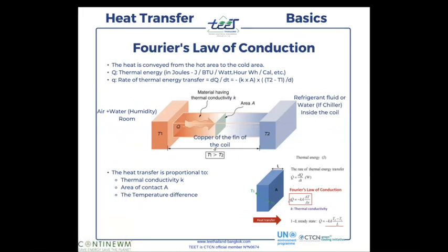You remember this, the quantity of energy is proportional to the delta T. Here you have T1 that is hot and T2. So if you want to measure the quantity of heat, that means the energy that is consumed by your AHU, how much the water absorbs the heat, which will result in the end on how much the power consumption of the chiller, you need to measure the delta T.